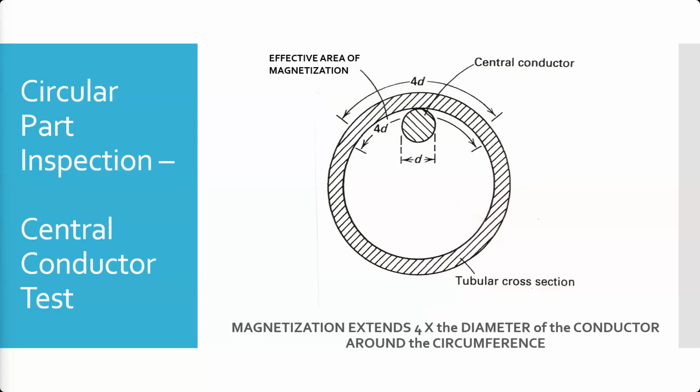So sometimes this works out nice and easy where we rotate 4 times: you do 1, 2, quarter, half, full. Sometimes it's a little more complicated where you have to do 5 rotations, right? So you can see that if we had a bigger rod, say a 1-inch diameter, this would be 9.42 divided by 4, and we'd end up with 3 rotations. We'd do it about a third of the way each time.